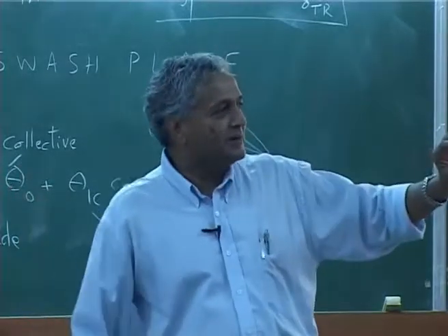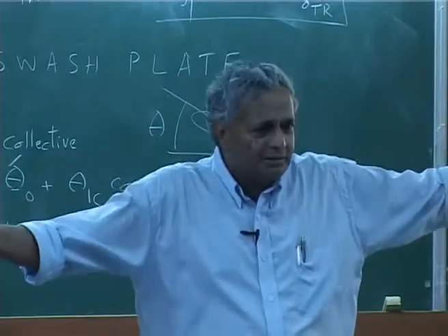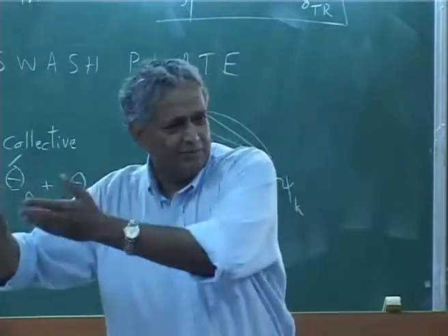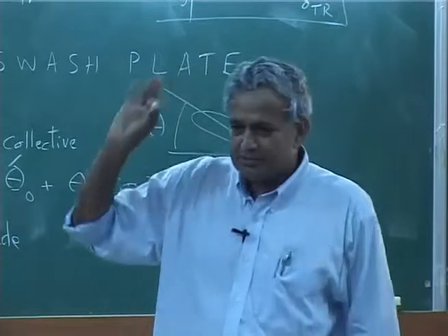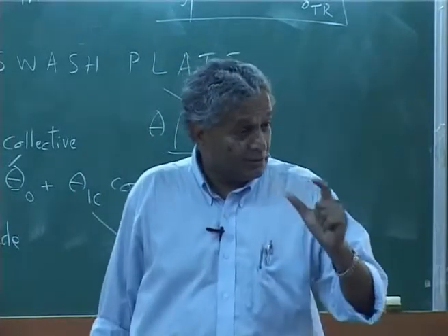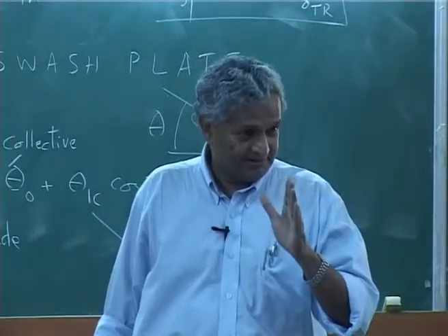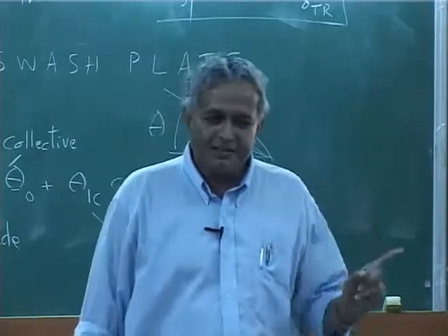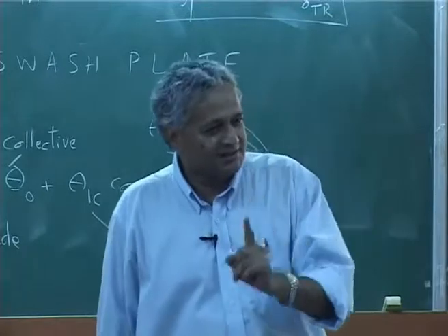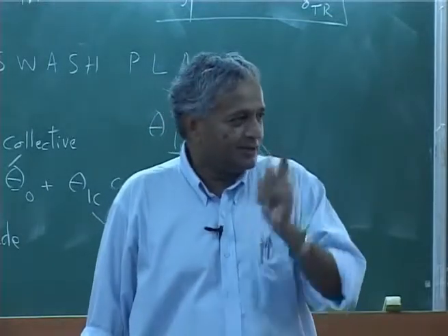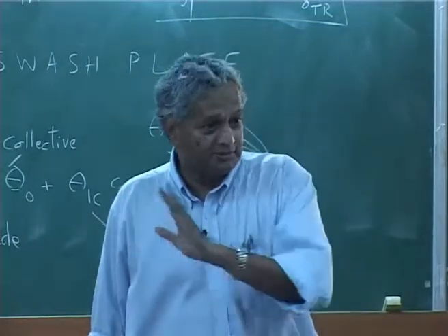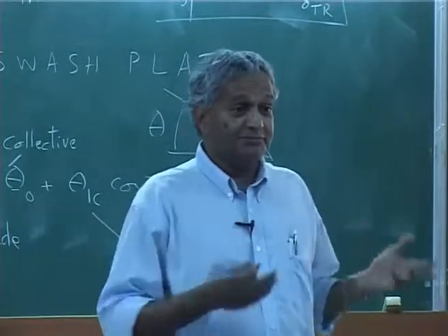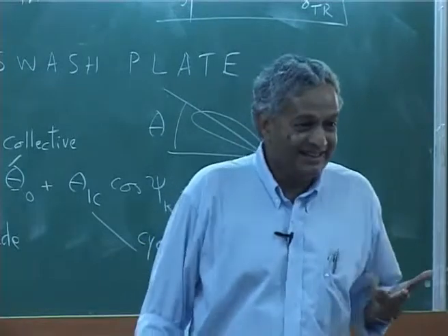They said I will remove whatever is a metal blade in the current helicopter and put a composite blade. That alone took 10 years, please understand, just replacement of a blade, because of the complexities, the whole dynamics, the structure, the aeroelastic problems. Now it is a new set of problems.